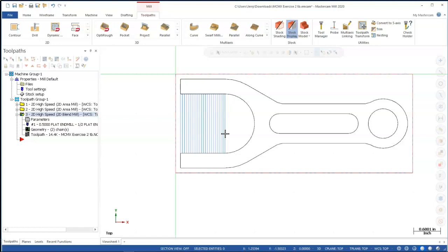Again, as the machines, you get into 10,000, 12,000, 15,000 RPM spindles, we're going to be able to up those surface feed per minute rates, increase the feed rates, and not do any, say, significant damage, any increased wear in your ball screws. It's going to be able to compensate and manage.